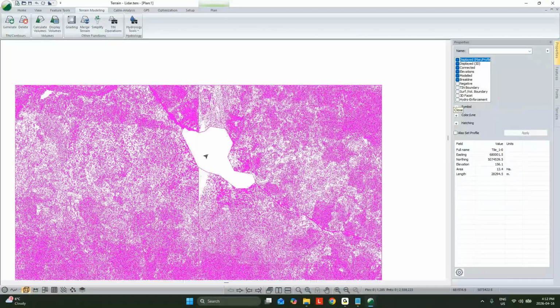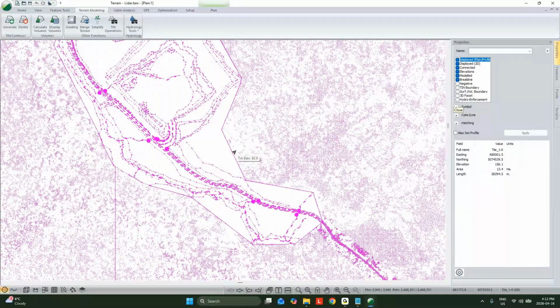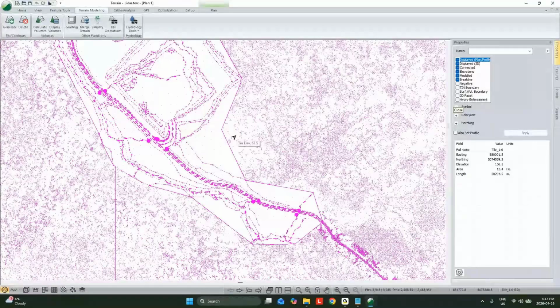So, and of course, combining data, super easy, especially when everything lines up. But occasionally there's biases as well. So if it was that my total station data happened to be on a different datum or something, we wanted to shift it up and down, and we'd do that check and moving things around before we actually hit the merge button. So yeah, it's pretty straightforward, but a little bit of extra work if things don't match up well. Hopefully that answers the question.